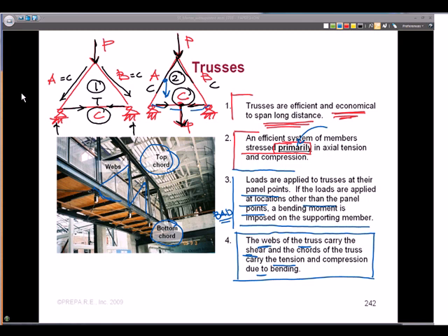And if you look at the active statics program, if we have a truss, where is it going to be critically sized for the chords? Well, it's going to be probably at the midspan where the bending would be the greatest. And where would the webs be the greatest in size? Probably near the ends, near the supports, they're going to be the biggest.